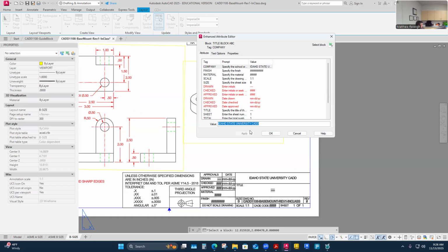Surface finishes fall under the same category as decimal places and accuracy. If you're expressing excessive amounts of surface finish control, then that's also causing additional work downstream from you. So you do want to know what is a general purpose surface finish, because it could be for a lot of parts that you draw.